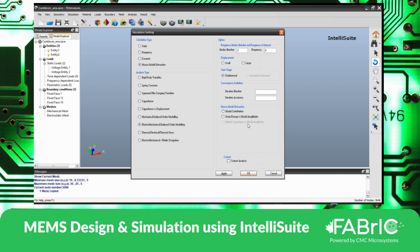I did mention that a dynamic based simulation is a huge time consuming activity in terms of FEM. In the case of the macro model extracted file, it would still be not more than a minute, because the FEM file gets converted to a lumped model file, and we can always extract more information with a shorter duration.